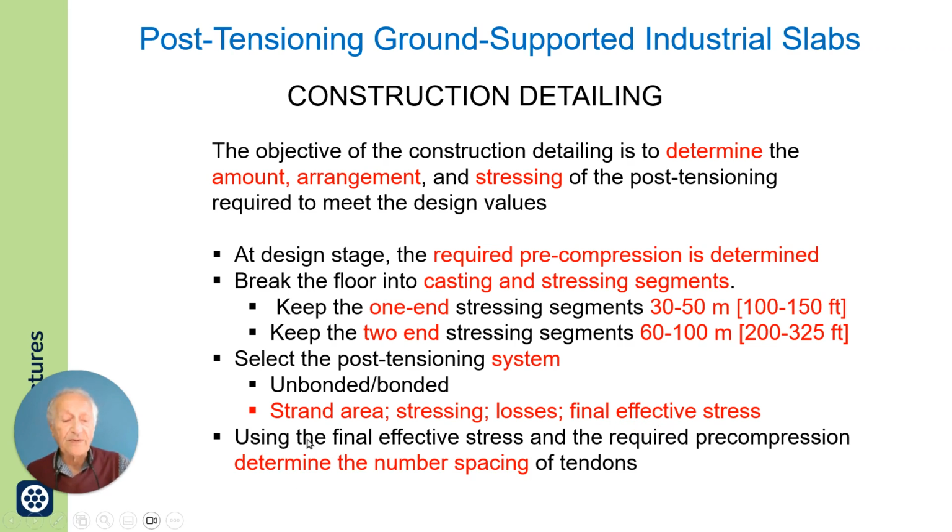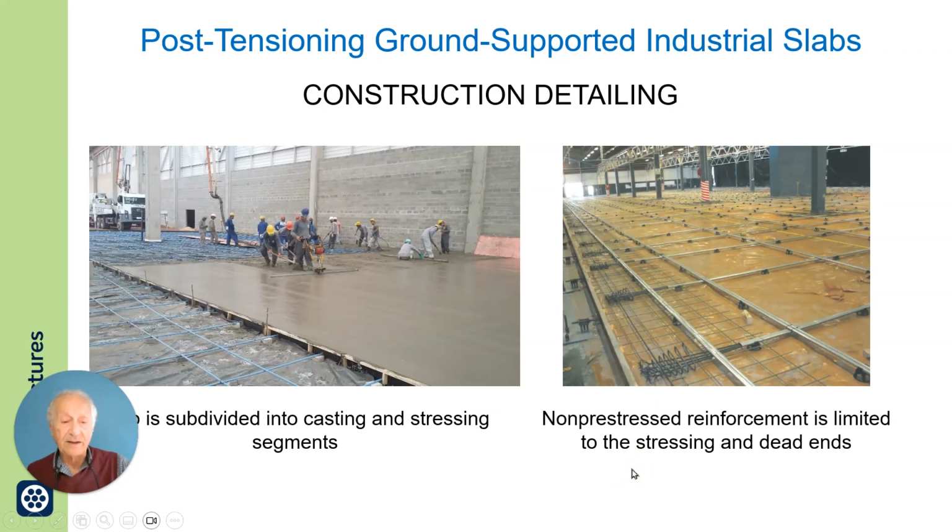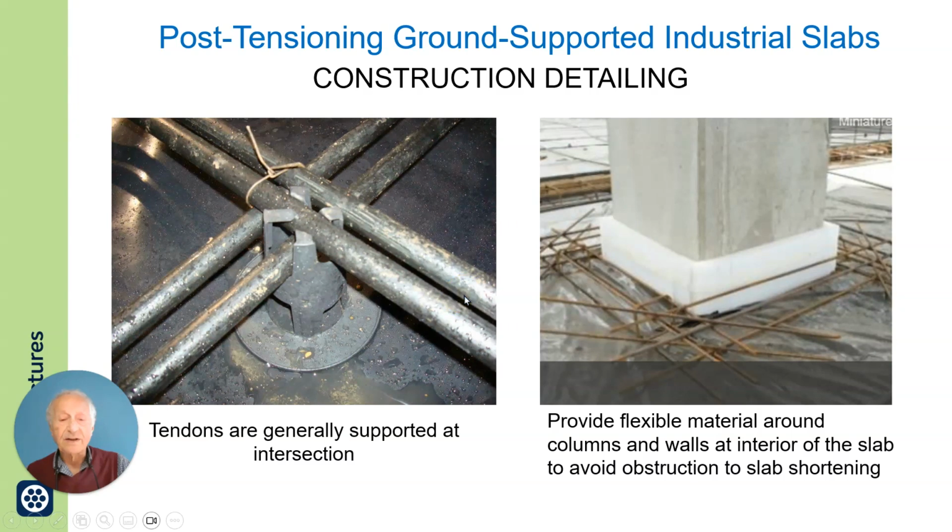You use the final effective stress and the required precompression to determine the number and spacing of tendons. Again, here I have another example of having subdivided the slab into segments for casting and stressing, and one which is ready to receive a concrete.